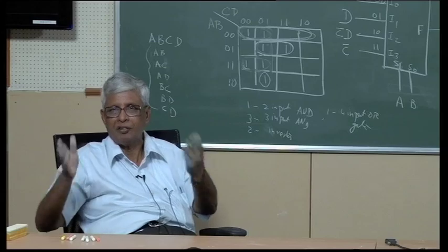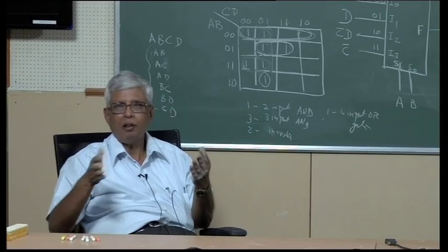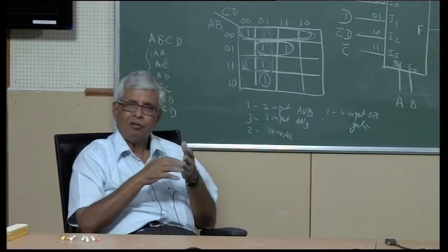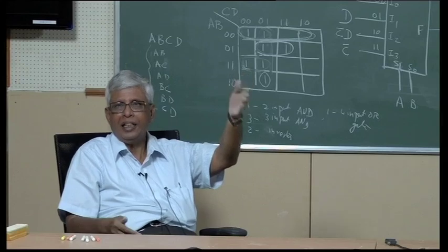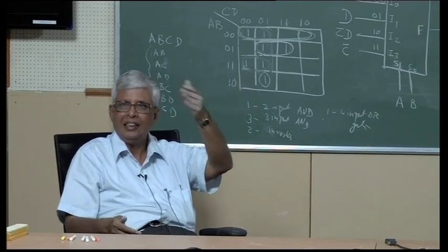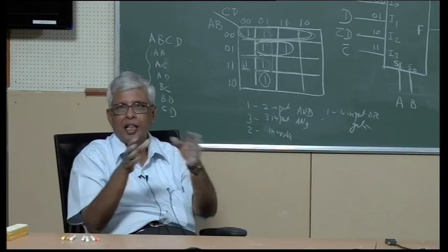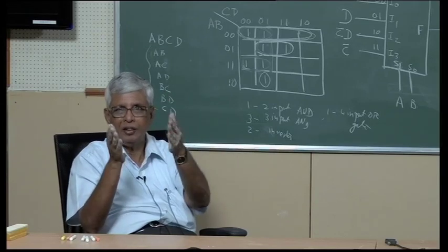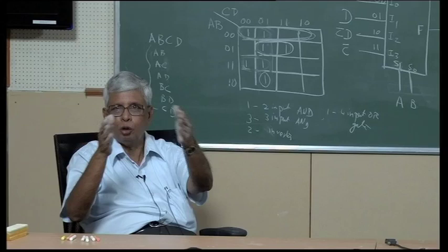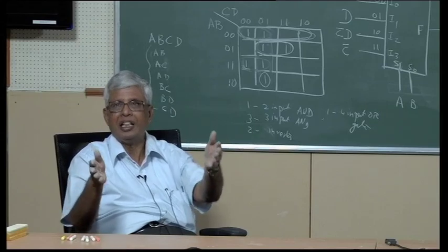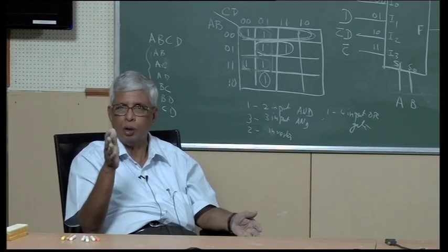It is called persistence of vision. So when you have one line, first you refresh one display, then you refresh the second, then third and fourth and come back to first, it will still be on, because we have this persistence of vision. When you have a display, it stays for some time, it does not immediately go out.